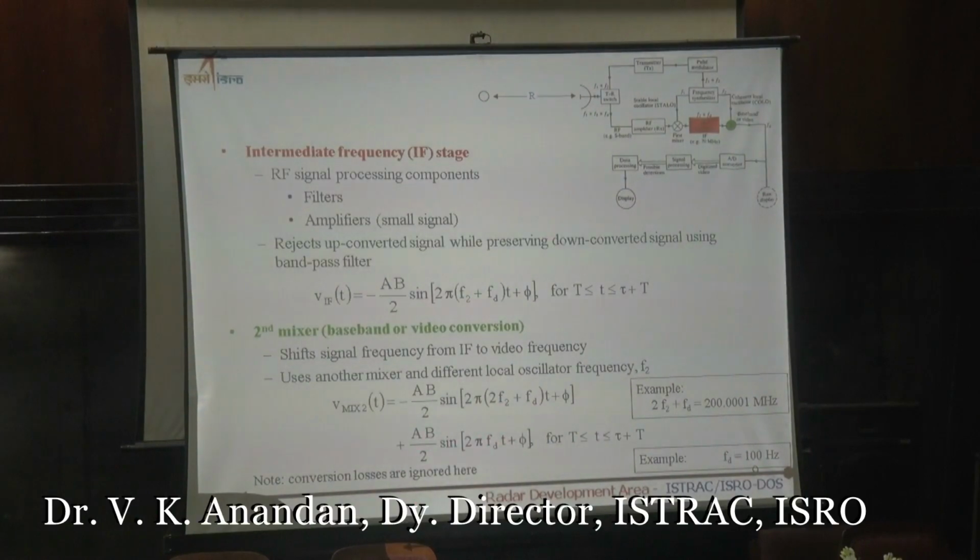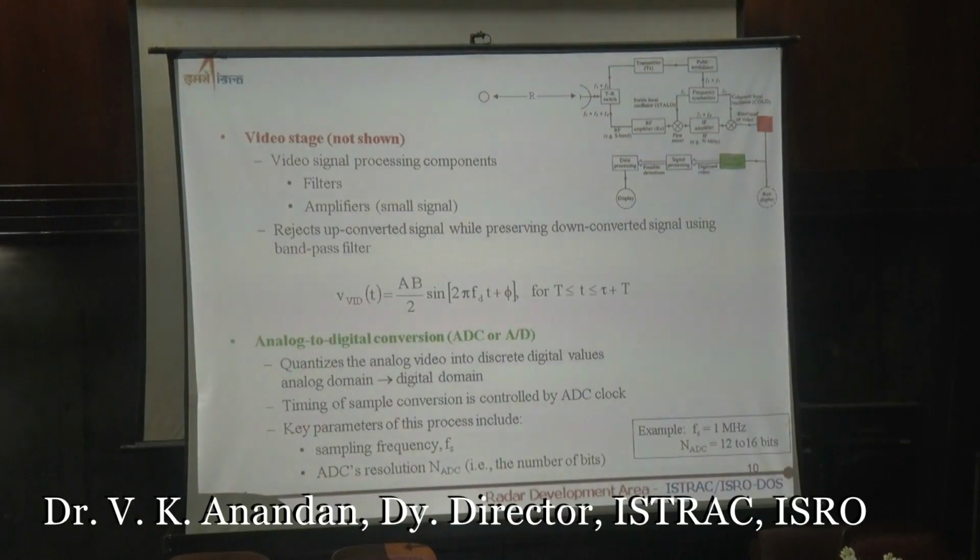This is looking back at your radar principles. This talks about the velocity, and how you extract all the components. Every time you can see the block getting shifted in color where it is acting. Once you get the Doppler shifted signal, you can take the IF signal directly, or in the new generation systems, the carrier plus F1 plus F2 plus FD is digitized straight away. An analog to digital converter converts the analog signal into the digital domain. That is all from the system point of view.